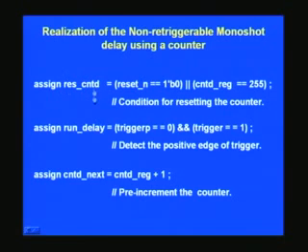And this one we have noticed that input is trigger, and we want to sense the rising edge of the trigger as such. How do we sense? One way is to put always at positive edge clock, and there you can't have more number of clocks. Maybe in any system you need to restrict it to say 2 or 3 clocks, and don't cross that number. So what do we do if you have so many other signals which also need to be sensed at the rising edge, or for that matter falling edge?